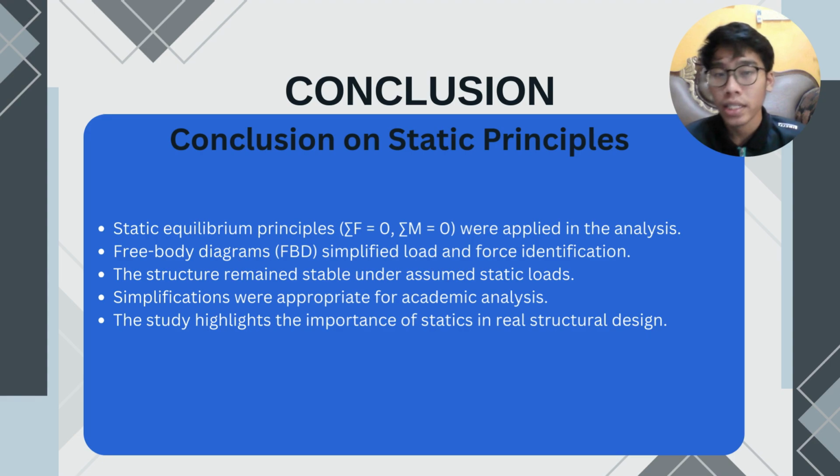The next slide is about the conclusion on static principles. In conclusion, this project clearly demonstrates the application of fundamental static principles in analyzing a real-life pedestrian walkway structure. The principles of equilibrium, where the sum of forces and the sum of moments equal zero, were applied to determine reaction forces, shear forces, and bending moments acting on the structural elements. Free body diagrams were used extensively to simplify the structural system and to clearly identify load paths and force interaction.